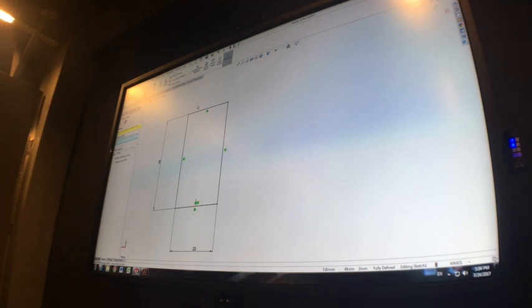And then you've got a couple of ways of selecting which places to add your fillets. The first, you can select 2 lines, and you see the yellow preview between those 2 lines. The second is to select a corner point, click on a corner point. Or the last is to draw a selection box over all of the fillets or corner points that you want to include.